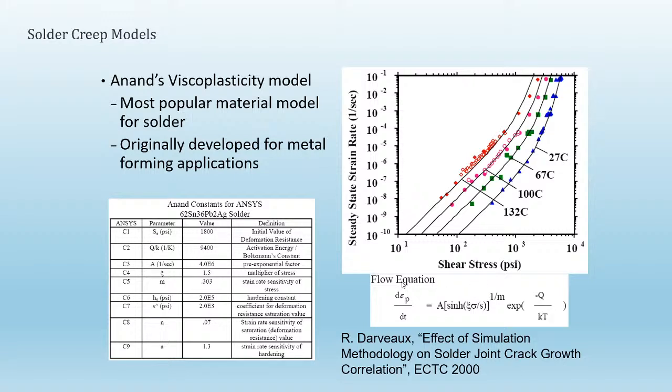You can see here the equation itself is a hyperbolic sine model with all the terms here fit into the equation. This equation, I believe, is from maybe one of the Ansys papers, or probably from the Darveaux paper, but the Ansys documentation will have this information as well.